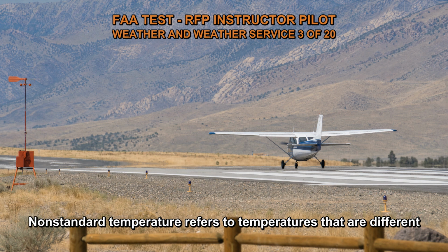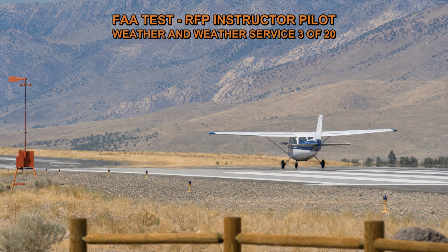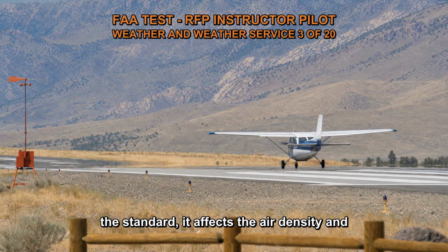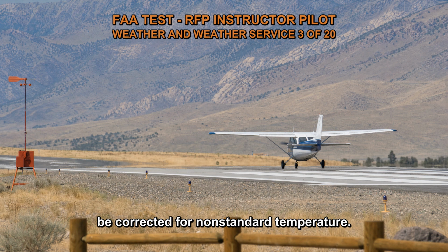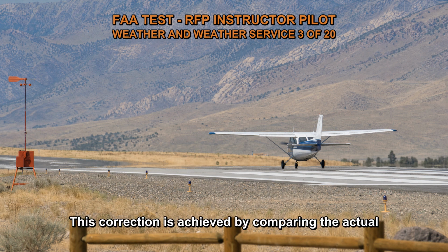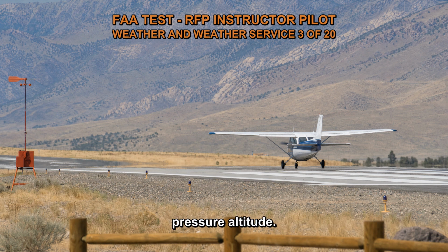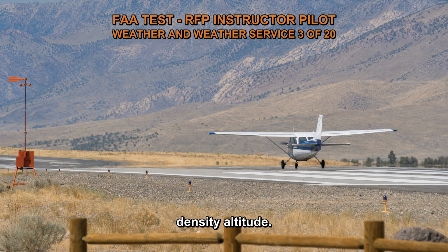Non-standard temperature refers to temperatures that are different from the standard temperature for a given altitude. When the temperature is warmer or colder than the standard, it affects the air density and subsequently the aircraft's performance. To determine density altitude, pressure altitude needs to be corrected for non-standard temperature. This correction is achieved by comparing the actual temperature to the standard temperature corresponding to the pressure altitude. The temperature difference is used to calculate the density altitude.